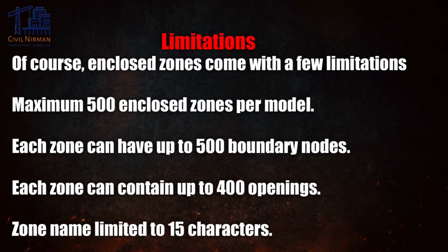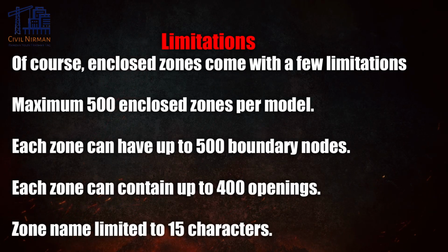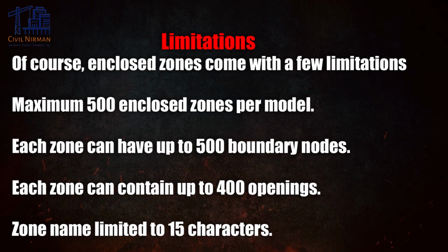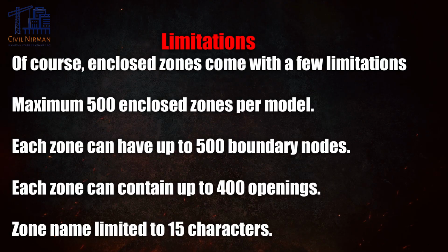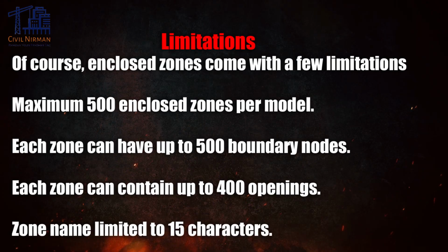And here are a few limitations that you need to take care of while creating your STAAD models. Of course, enclosed zones come with a few limitations. For example, maximum 500 enclosed zones per model. Each zone can have up to 500 boundary nodes. Each zone can contain up to 400 openings. Also, the zone name that we specify is limited to 15 characters only.